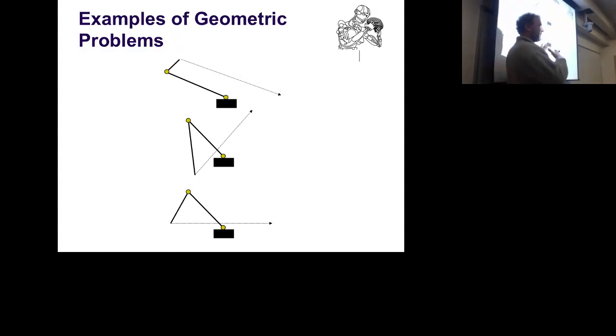And if you try to solve for this trajectory with inverse kinematics, you will basically at some point get a Jacobian which blows up, and you know that something didn't work. If you have problems like that, you cannot do simple planning anymore. You have to think harder how to get around, and that usually goes into the world of AI style planning and search, and is much more complicated.